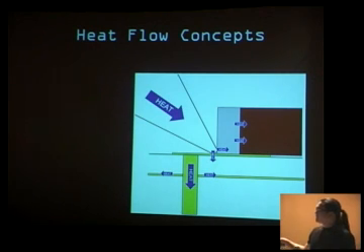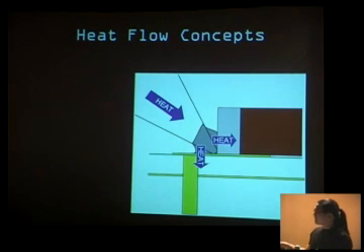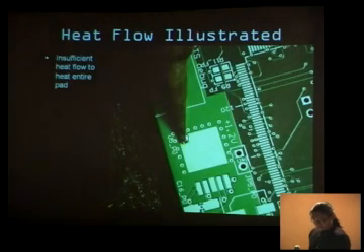So what happens when they add solder is that the solder beads up on the component, and nothing touches the circuit board, and there's not actually a connection going on, right? So a lot of times, to increase the heat conduction, before you even start soldering, you put a little bead of solder on it, which creates a liquid meniscus around the whole joint. That causes a much greater area for heat flow, distributes heat more evenly, and you get a good solder joint out of it at the end.